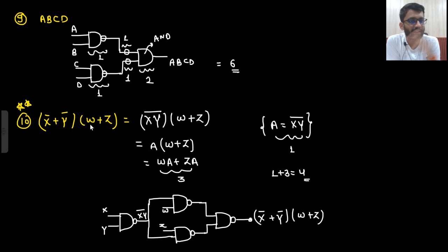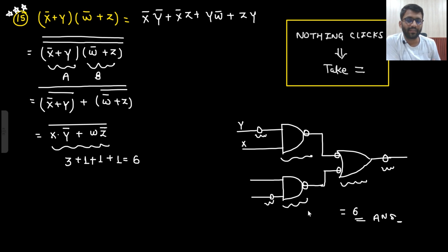Okay, we will see it in the next lecture or in this lecture only, because time is passing. So this is equivalent to XOR gate, and this is equivalent to XNOR gate. XNOR gate can be implemented using 5 NAND gates only, but this is being implemented using 6 NAND gates. That's why I'm expecting this example can come.